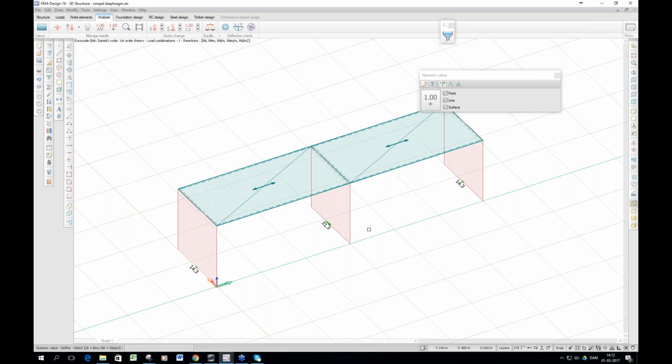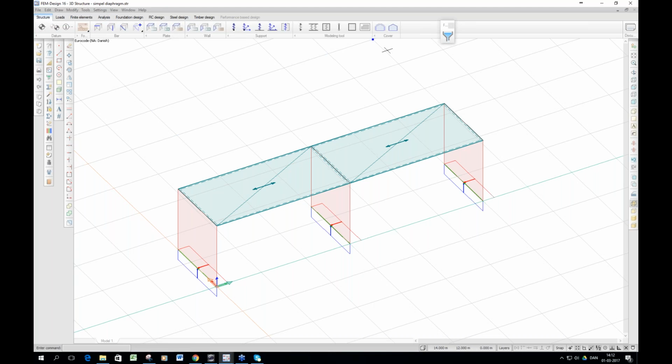But when we calculate prefab structures' stability, we normally just say that, okay, we might use the moment of inertia, the ratio, and distribute the loads according to that. So this is what the diaphragm does. If I go to structure, I'll apply the diaphragm. It's one of the most simple functions we have. You can almost not make it wrong.